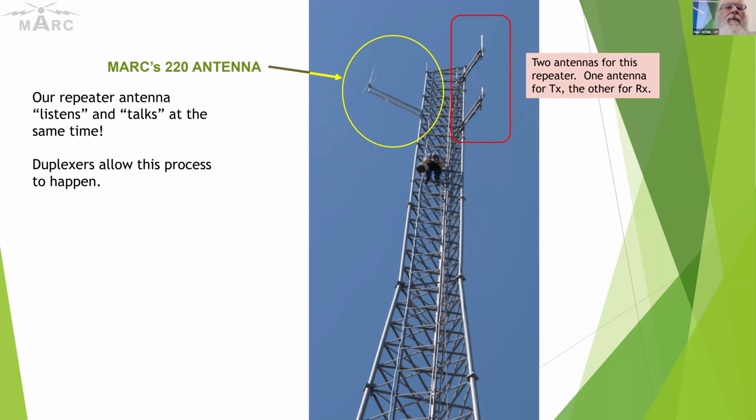Okay, so at the very top, they've stripped away the heliax sheathing and tied that copper corrugated braid, if you will. On regular coax, it's braid. On heliax, it's solid. That's why they call it hard line, right? And that is bonded to the tower. That same bond happens at the base of the tower and before it goes into the shack. So everything is bonded together.